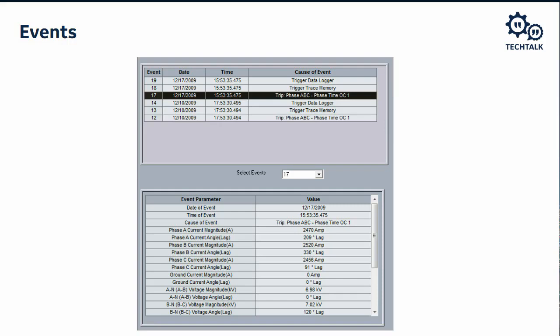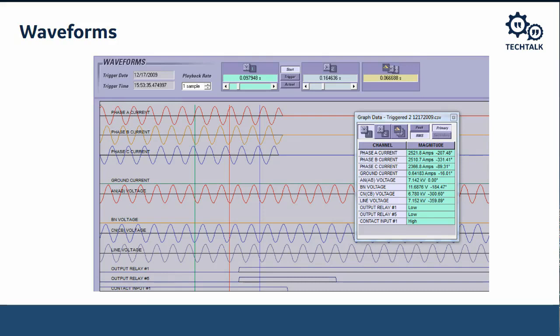Let's take a look at the phasers. Since we have them, we can. Let's take a look and see what they look like. Same thing. Phasers look healthy. I don't see any real distortion in the waveforms. The A, B, and C phase currents are at the top. So I don't really see any distortion in the waveforms. This looks like a legitimate trip. And I would want to trip if it's 2,500 amps.